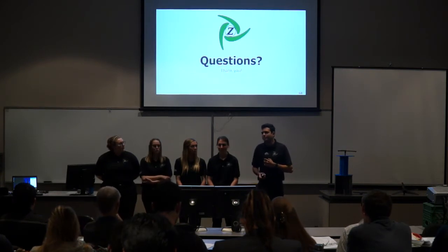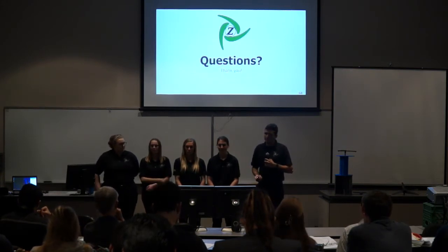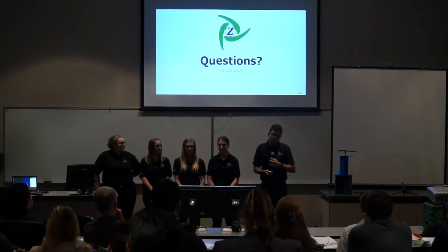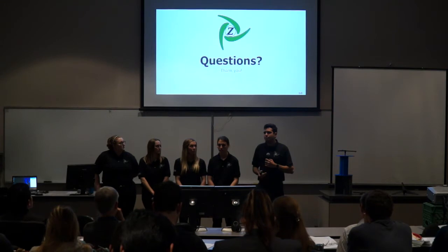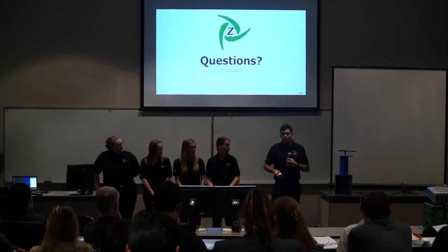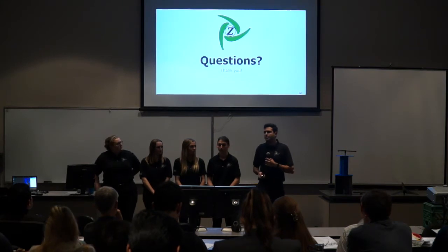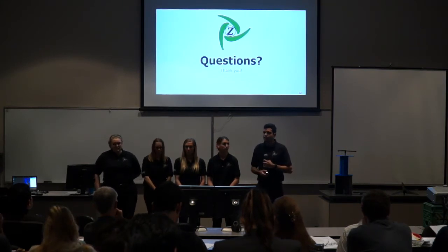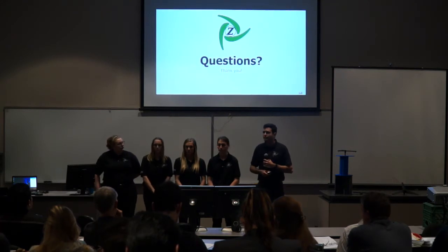Because 3D printing has clearances, we did this as an experiment to see if just printing it as is would help, but we do have to alter the design a little bit. We tested the hot design, the one on the table over here, with a clearance of 0.05 millimeters, and it has a perfect press fit into the system. So with the set screw, it should hold it in place. So that's what we're going to do for next semester.